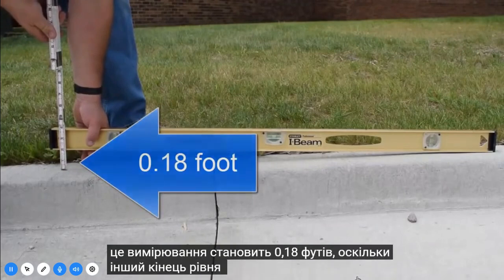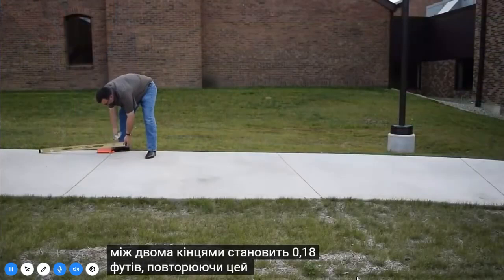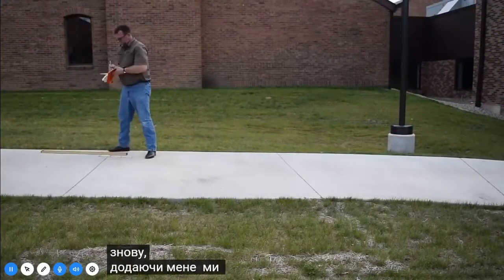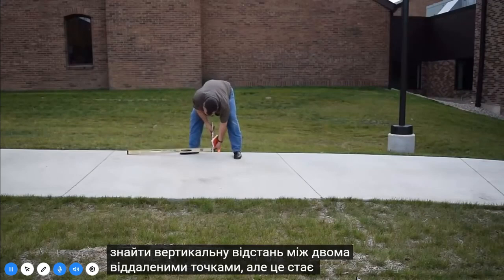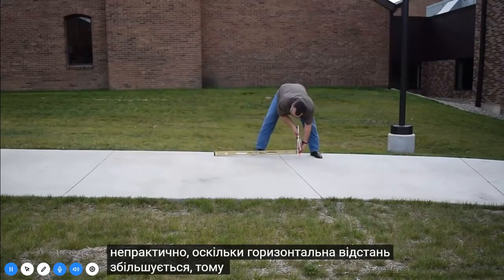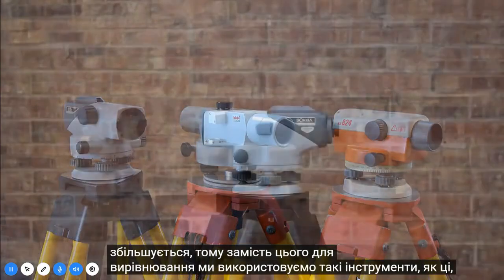Since the other end of the level sits on the concrete, the vertical distance between the two ends is 0.18 feet. By repeating this process over and over, adding measurements end to end, we can find the vertical distance between two distant points. But that becomes very impractical as the horizontal distance increases. So, instead, for leveling surveys, we use instruments like these.